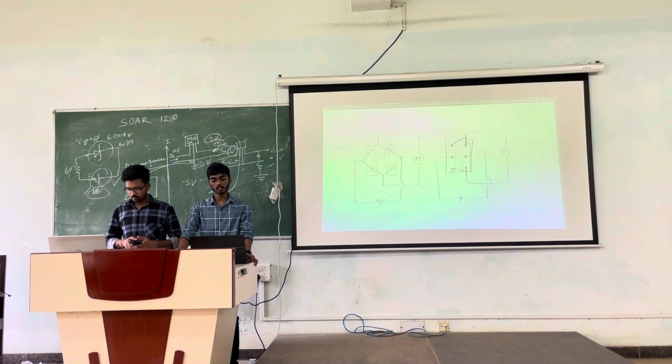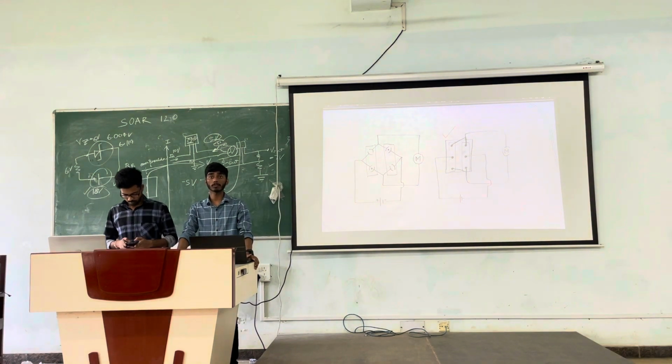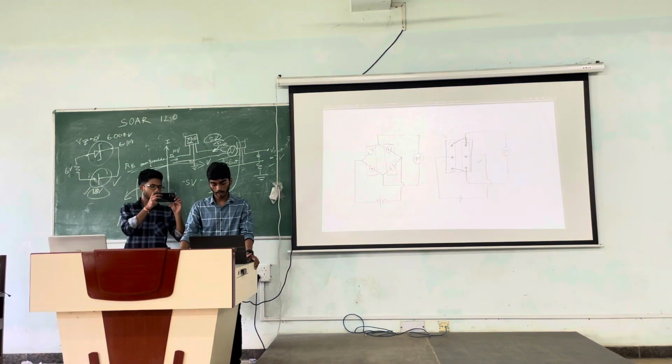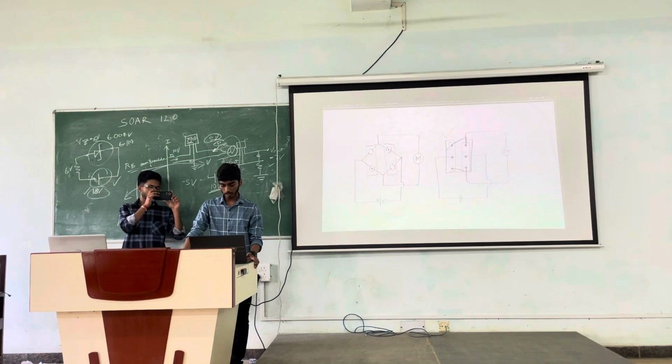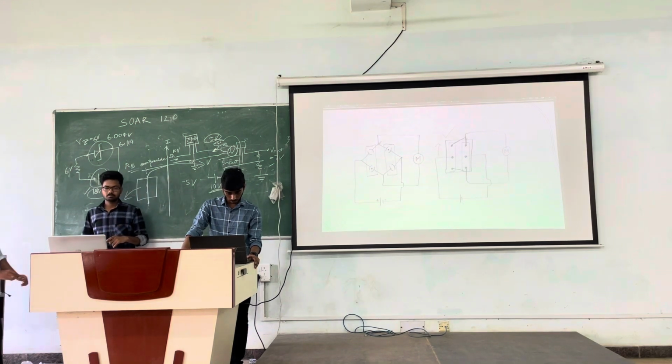This is basically just our DPDT switch as seen from the top. Okay, so this is the top view of the DPDT switch, and if we toggle it that way, let's say, suppose, what happens? We basically have 6 terminals in a DPDT switch. So we are connecting the motor here. The motor is connected to this switch and this switch.